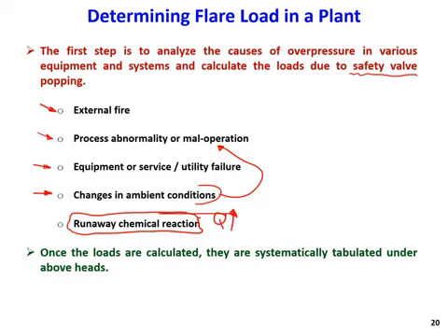So when we have a runaway reaction, that can lead to an increase in the temperature of the reactor, and the heat which is generated in the reactor will increase. So we will have a high temperature in the reactor, and this high temperature can vaporize the liquid. If the reaction is a gas phase reaction, pressure will increase rapidly, and we have to relieve that pressure, so we use some sort of safety valves to do so. Okay, so the pressure will increase highly.